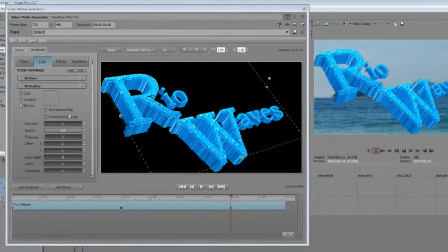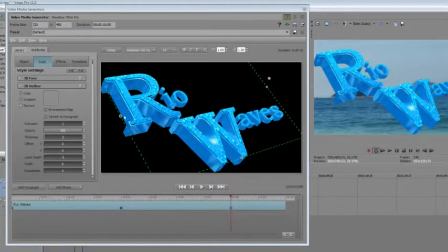What the environment map basically does is says, okay, treat my extrusion, or my face, whatever you're applying it to, but in this case I'm applying it to an extrusion, treat the extrusion as if it was a mirror, and then treat the texture that I've put on the extrusion as if that texture was applied to the walls around the mirror, around the room that the mirror sits in. So when I choose environment map, what I'm seeing is a reflection of that map, not the actual map.